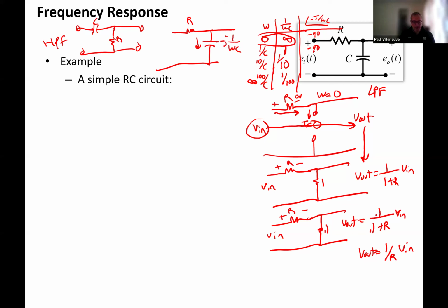You can do them, and you see them in higher power applications, like variable frequency drives, where you sometimes will see inline inductors. They're called reactors once they get to decent power applications, where you put them in line with your circuit. That provides a low pass filter, so it allows 60 hertz to go through, but nothing else. You'll see those at higher power applications where capacitors really don't have the same benefit, and can cause some other problems, but they would work perfectly fine.